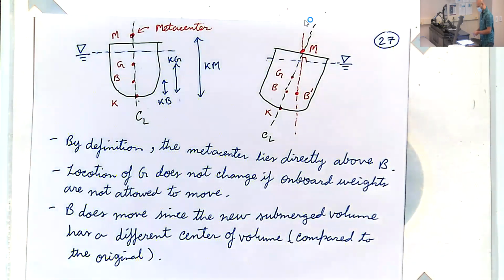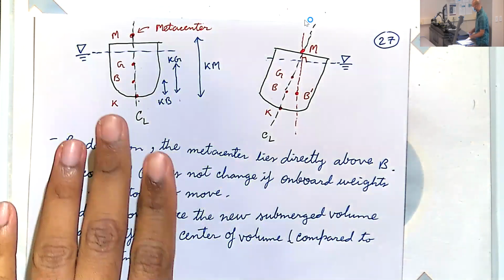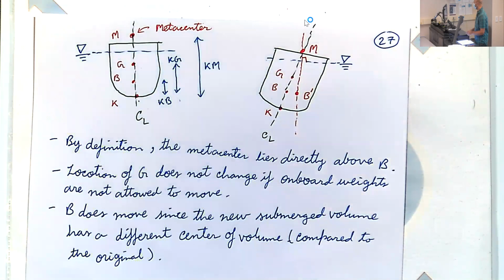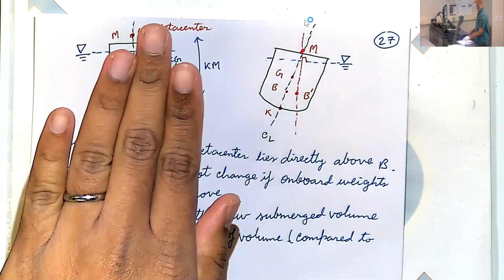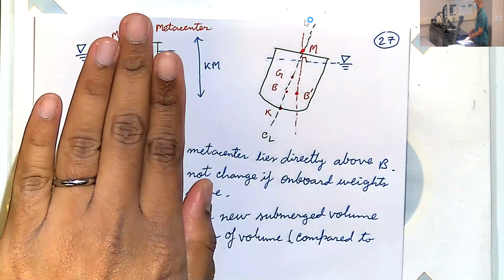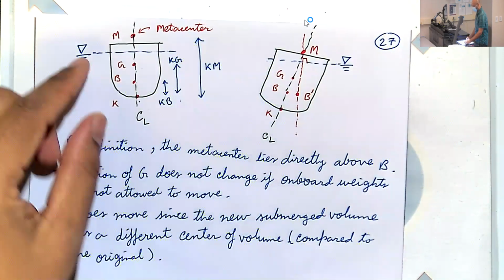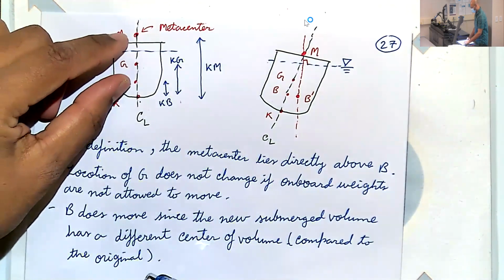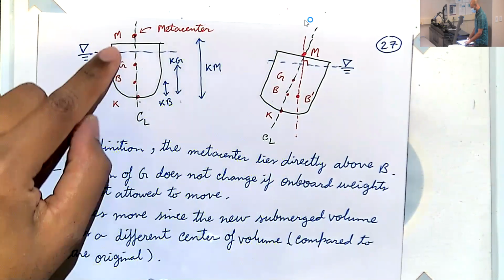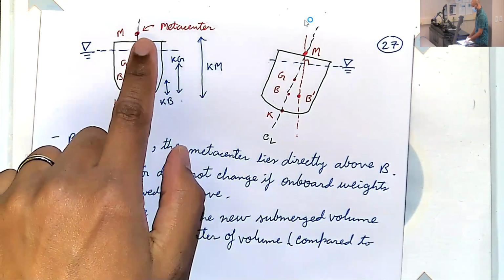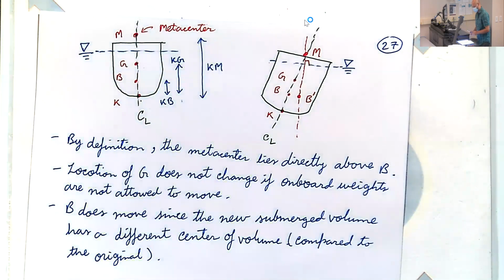Now, another thing to keep in mind is, if a ship is rolling, unless it's very rough seas, the roll is very gentle. You almost never go above, let's say, 10 degrees. So in that scenario, the distance between M and keel does not change as this very gentle roll happens. It'll of course shift a bit, but the total distance will remain more or less the same.